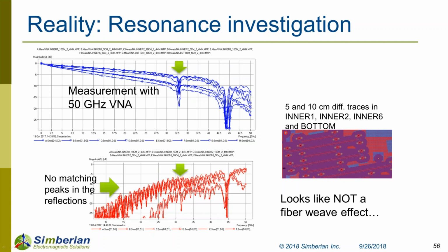So, for instance, for flat copper, I don't expect the additional losses and additional inductance due to roughness. And the latest trend, this HVLP, VLP copper, gives you additional inductance. That's what is captured by the Hammerstad-Bracken model, due to currents flowing in a relatively weird way. And there is a demo video on our website on how they actually flow.